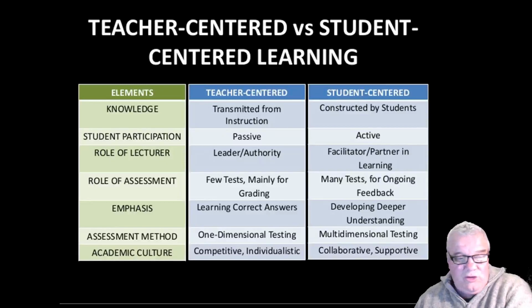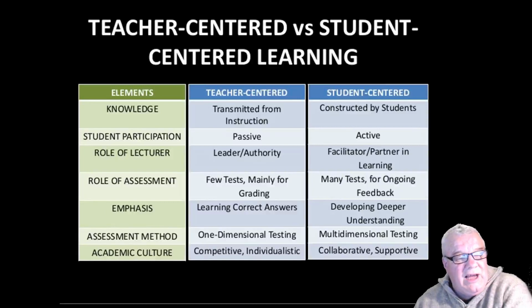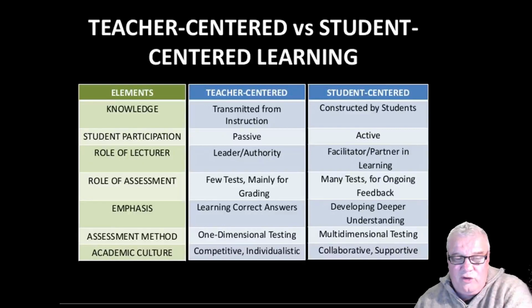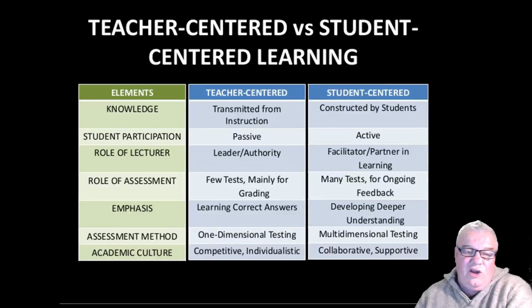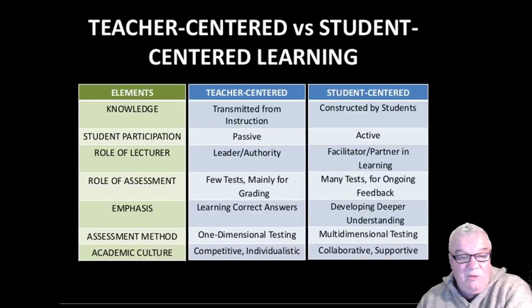And the 6H, well, don't even bother. So where do you use the 6H pencil? Well, you use the 6H for plotting coordinates onto cartridge paper or onto your plot sheets before you draw your plans. Now, this knowledge, as you can see, I know it inside out pretty well. However, we don't plot coordinates anymore. We can do that digitally. A lot of us are not using field notes at all. It's all done with data recorders and things like that. So while I can impart all of this knowledge, in terms of going forward, it's not particularly relevant.